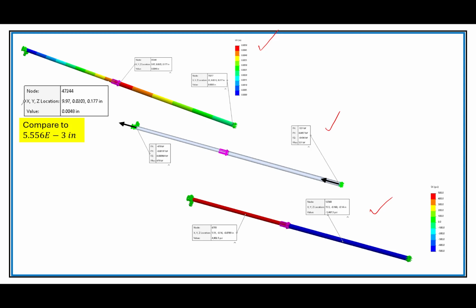So here is the displacement. Here is what I said my hand calculation would be. I might have meshed some additional things, but it's such a small element, such a crude thing. I used such a crude mesh that I didn't really expect them to match exactly. They're going to get in the ballpark.